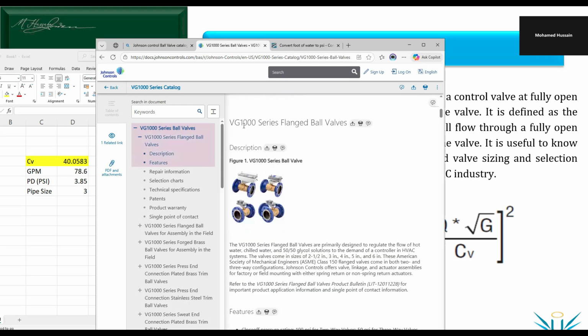Next, if you look here, this is a flanged ball valve. We said that for more than 2 inches, we can go for the flange type ball valve, and our line size is 3 inches. In this case, it is more than 2.5 inches. So we have selected the flange type valve, not the threaded type. Look here, flange is screw nut type.